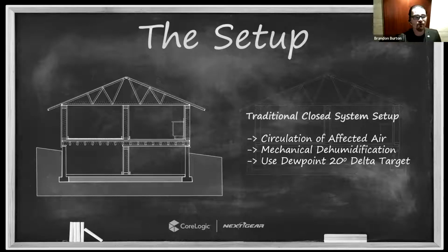You may also consider running your temperature in that basement a little bit lower, right? If your temperatures are 90, 95 degrees because of your drying equipment within that space, then you may actually need to bring the temperature down slightly, because that may be the reason why you can't get the grains low enough, especially using refrigerant dehumidifiers. In a future episode, we'll talk about refrigerant limits, but the warmer the air is in that space, the more difficult it is for a refrigerant to lower the grains.